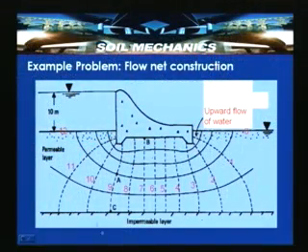So, this is an example of confined flow with a masonry dam resting on a permeable soil medium. Below there is an impermeable soil layer. So, you can see, here what we can do is that the first flow line can take place along this boundary. So, you will be able to get a flow line passing through this particular boundary.